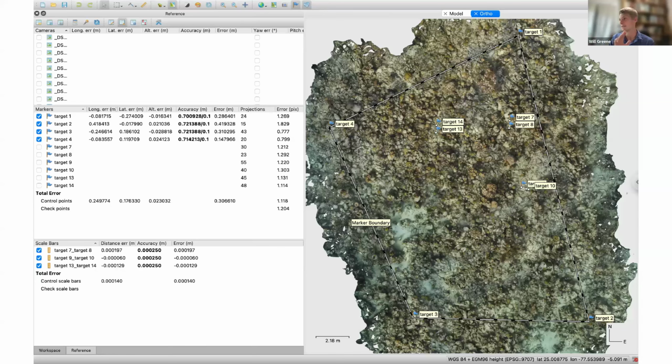And then you just hit OK, and everything runs, and it will fully georeference your plot and place it at the correct coordinates. It places priority on the scale because that's the most accurate and most critical measurement. And then using the depths from your dive watch, it will level your model as precisely as possible. And then finally, it'll adjust its XY location to match the GPS coordinates. So even if your GPS coordinates are lower quality, you still have very accurate scaling and very accurate leveling in your model.